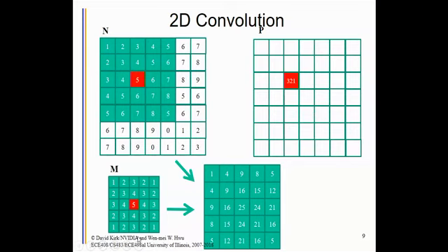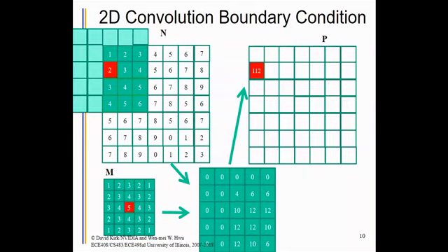So we usually will see floating point fractional values here. This is the reason why, if you look at a lot of the convolutional neural net implementations, the default implementation is always floating point numbers. And then if people want to save power, energy, and so on, they use what we call the fixed point implementation, which is exactly a fractional value, but not with floating point capability, dynamic range, and so on. Okay? So this is 2D convolution.